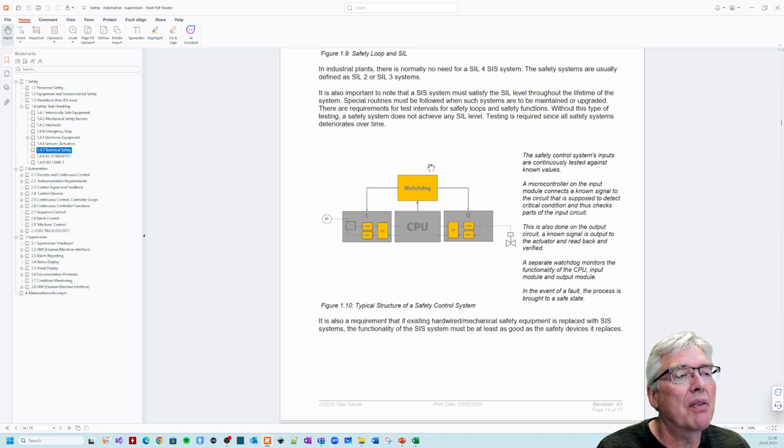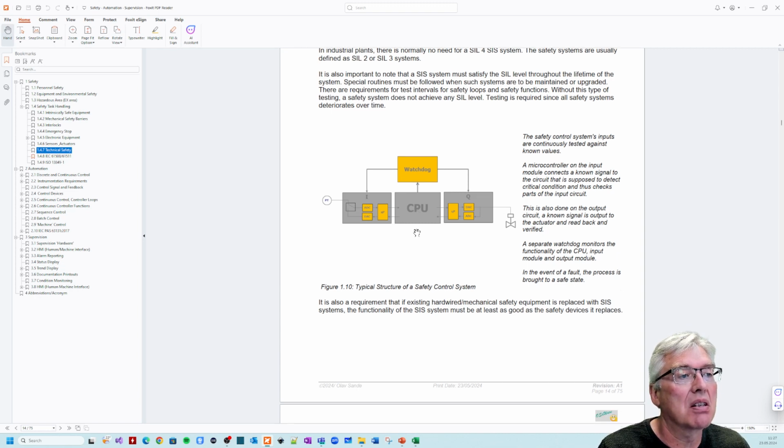And the CPU itself has a watchdog. So if your program doesn't reset some watchdogs at regular intervals, which means the program has stopped doing its task, a watchdog is triggered. Usually the CPU just shuts down and the entire system shuts down, valves open, or if they fail, valve closes. If they fail open, they open, whatever should do here. If it's emergency cooling, for instance, by heat in a tank or something, the valve would open. So then we have cooling, if this system is doing cooling.